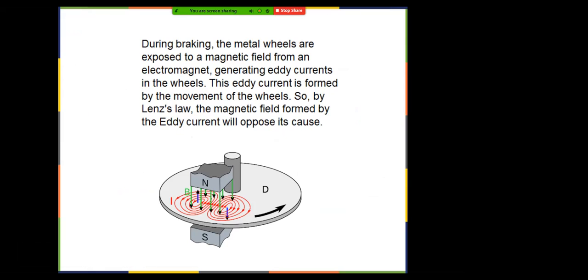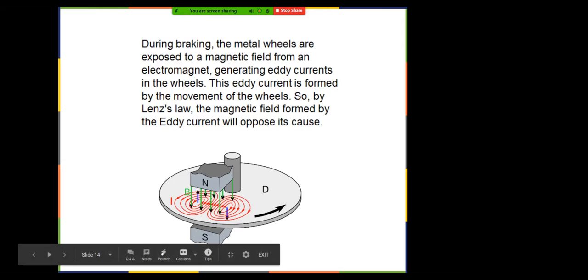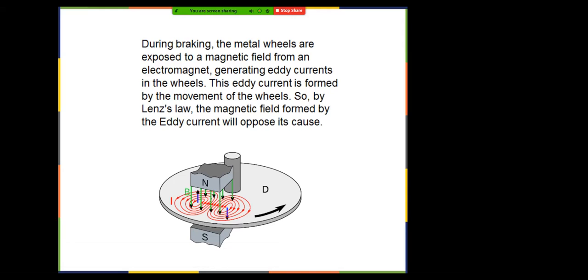One application would be the electric brake. When that is applied, current is sent through coils on the two sides of this metal drum, which produces a magnetic field. The drum is moving inside the magnetic field, so eddy current will be produced on the drum, and that will produce a drag force on the rotation of the drum, which slows down the wheel.